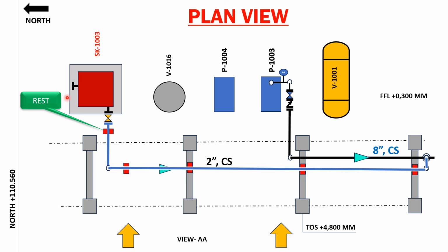So there are different types of support. Rest support is the one which supports from the bottom of the piping. Understand? Now why am I going to provide a rest support over here? Because here I don't want to stop the movement. This point is already anchored, so the equipment is anchored. I don't find any sideways movement over here. The only thing is that it needs to support the nozzle loading basically. So I have to provide a rest support over here.